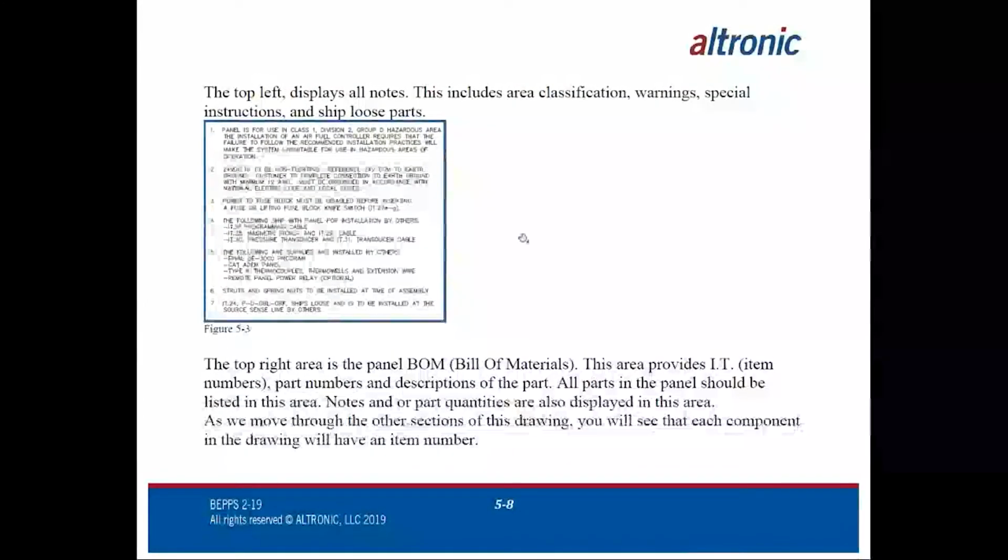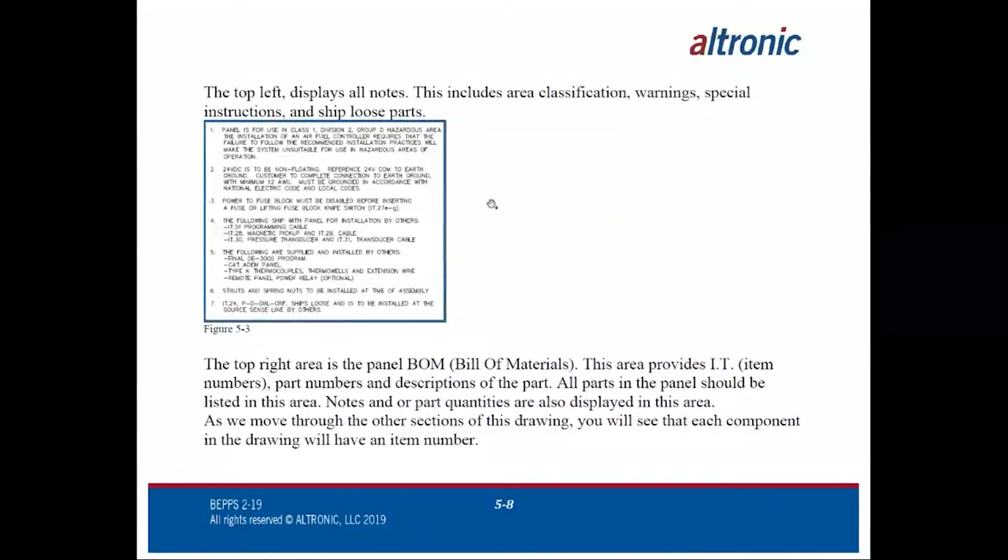The top left of page 1 is generally reserved for notations, notes. So if it's a DD40 annunciator panel, it'll even have basic programming information in that area. There'll be numerous marks within the drawing that always reference C note 7, C note 5, etc. Sometimes it's just general information. Sometimes it's something that's about parts that might ship loose with the panel. Sometimes it's about the fuse.